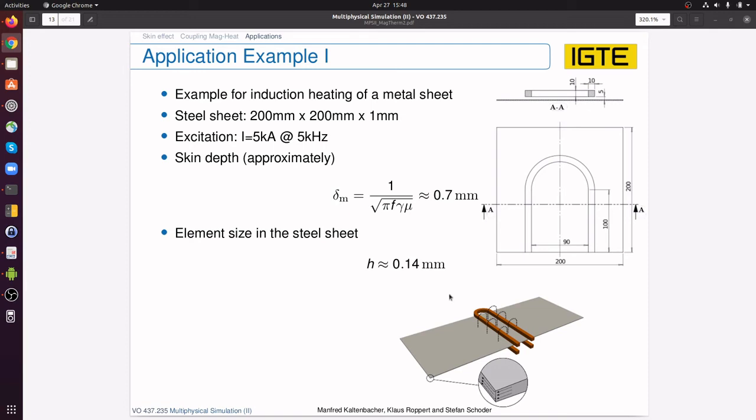And this is especially true, not that much for these thin steel sheets. It is way more dominant if you have some, I don't know, thick axle or crankshaft, so some solid piece of steel, and if your inductor is wound around the piece to be heated, around the solid workpiece, then you have some massive dynamics going on, and this workpiece then couples back into your electrical circuit much more severely than this thin sheet does.